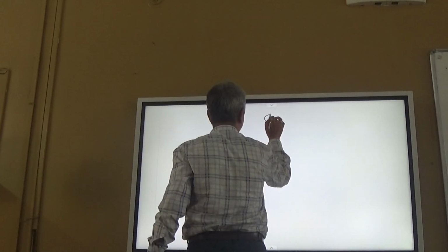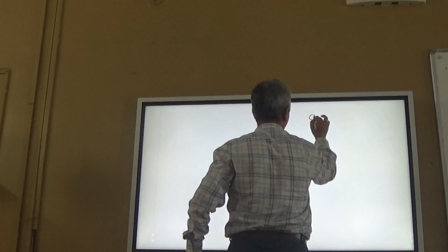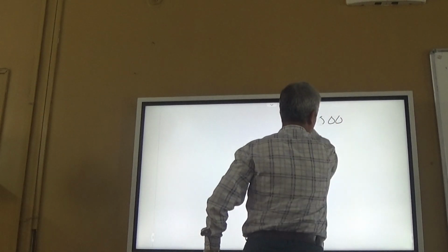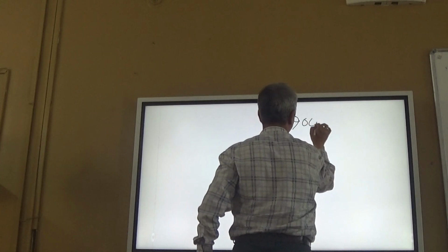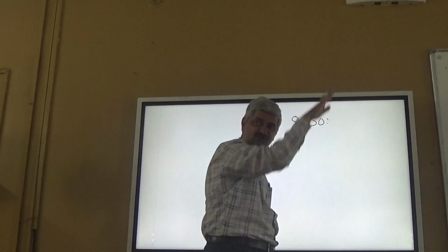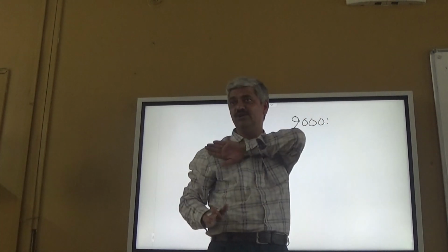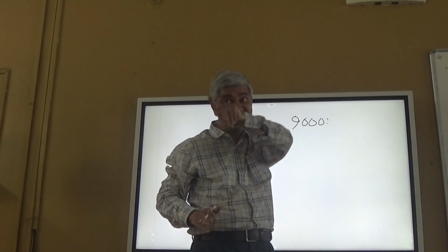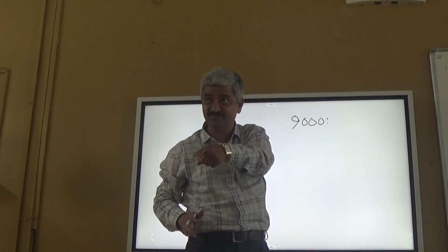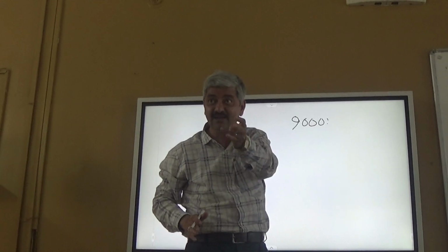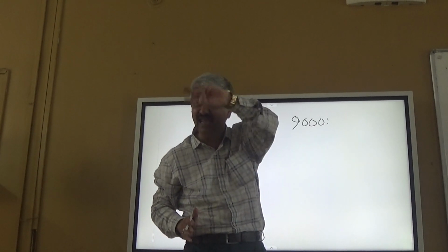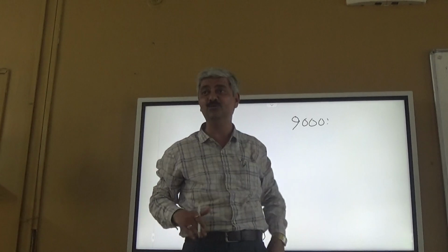So what I can do is, at 9000, before starting the actual multiplication, I will store everything except HL, because HL I want to change: B, D, and the accumulator with flags, AF. So I will push them.